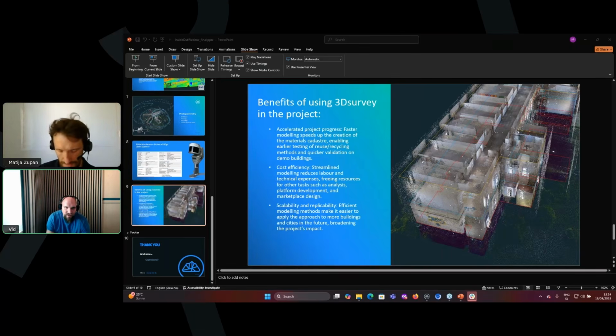Then one trick you can do in 3D survey, we did it like that. We colored different point clouds differently. One would be blue, one would be red, one would be green, etc. Then we would do a cross bounding box and take a very narrow slice, and look at it to see if we get any double walls. Double walls would be an indication of an error in georeferencing. If you see errors there, you can add some additional data and try to get it to georeference properly. So basically, I would do a visual inspection of the point clouds georeferenced together, and make sure that one point cloud doesn't have a different position from the others.